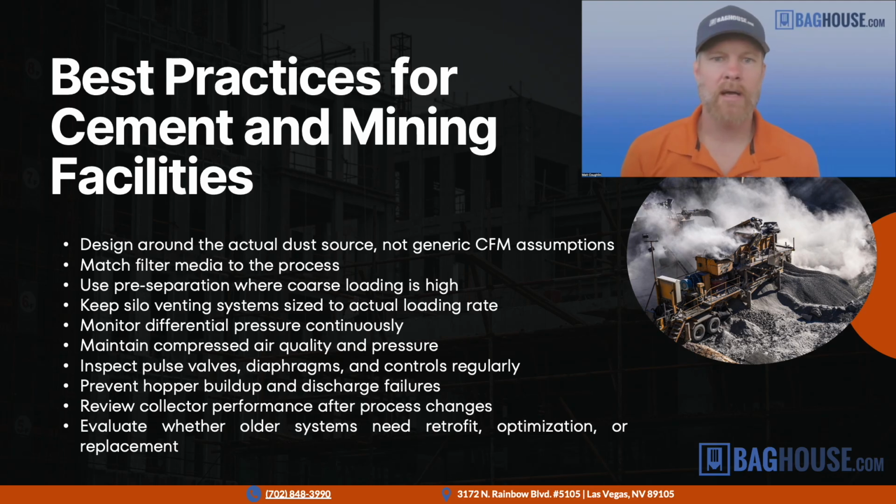So just to kind of summarize from the presentation today, there's a few important points. Number one, the dust collection system should be designed around the actual dust source. So it shouldn't be just a generic airflow number, CFM, and run with the dust collector. The reason is the hood design, the material behavior, the source dynamics at your particular part of the process are really important to making sure that the dust collection system performs as you expect it.